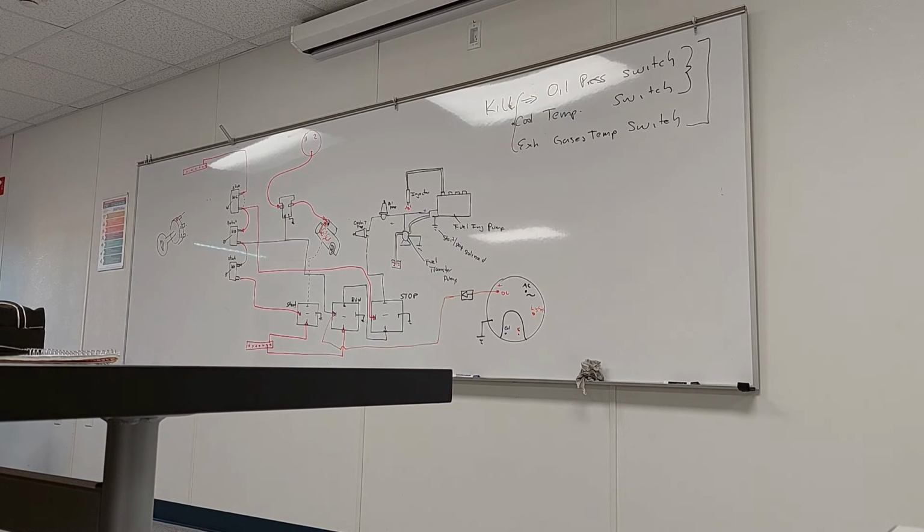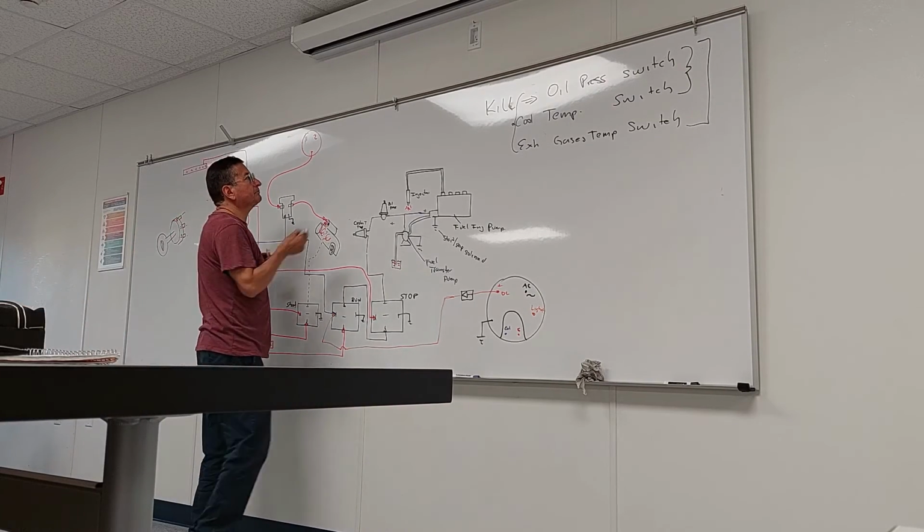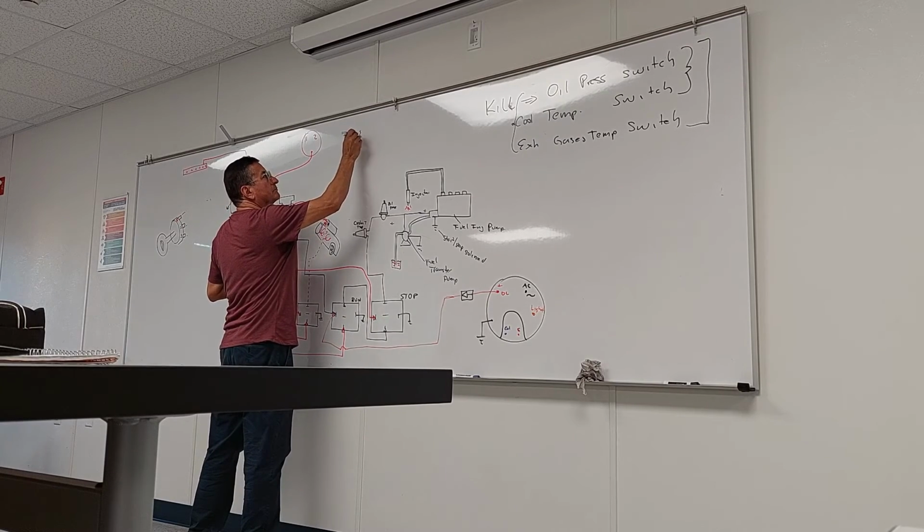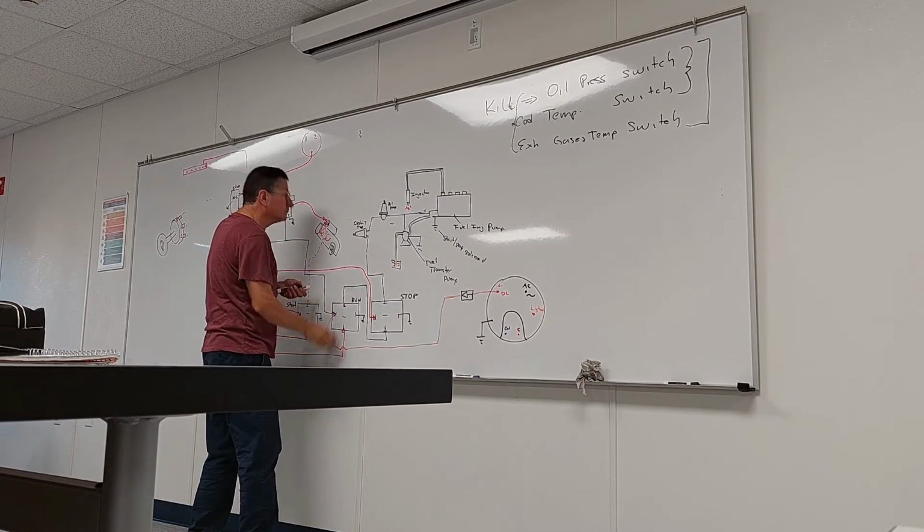So I'm getting a little bit confused about the oil pressure switch. Do you press it manually, or is it like a sensor? Does it turn off by itself? It's under pressure, like a spring. The pressure pushes on the spring and allows contact. If it loses pressure, it loses the contact.